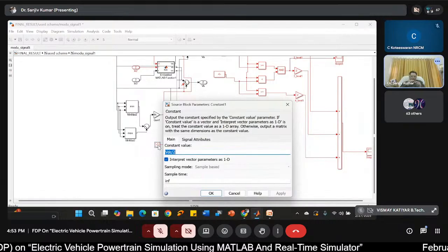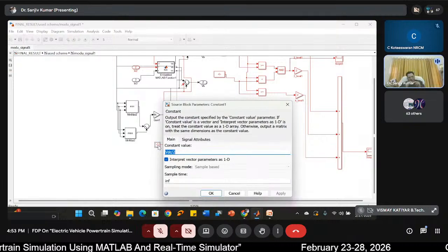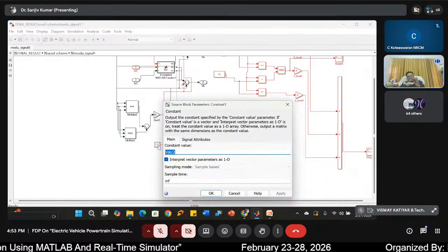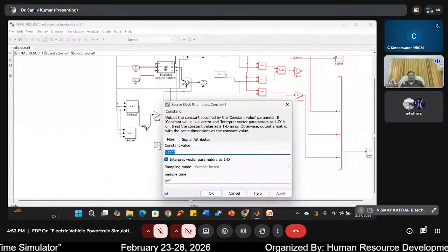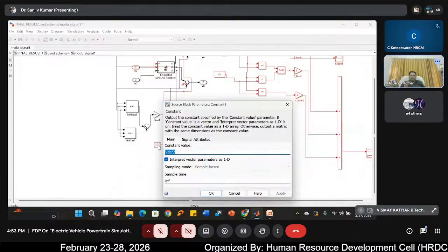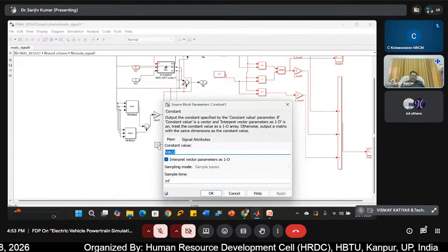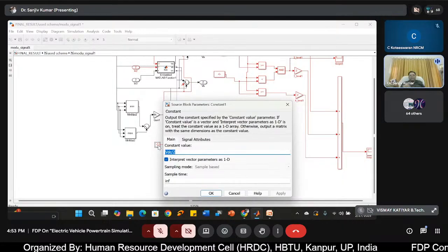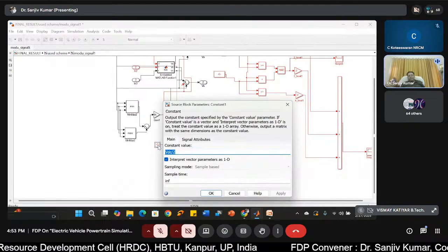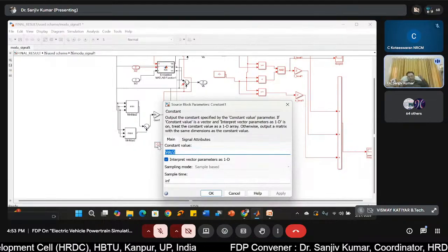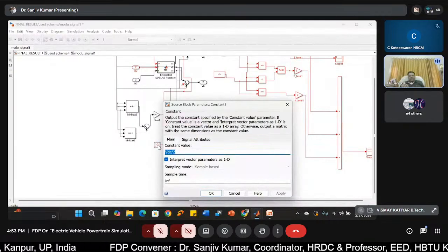That means from 0 upper 4 triangle, and from 0 lower 4 triangle, and you put your sine wave here. In that case, the switching losses are higher. Rather than doing this, first you put that triangle at the lower level. Let us say it is of 0 to VDC by 8. Let us say for n level inverter, each height is 0 to VDC by 8.